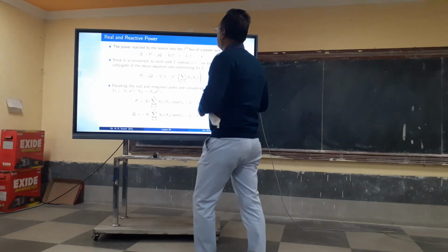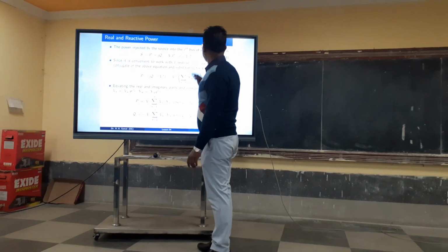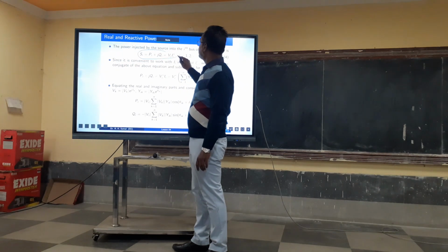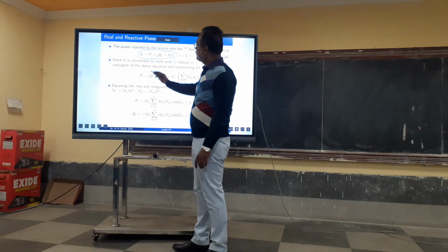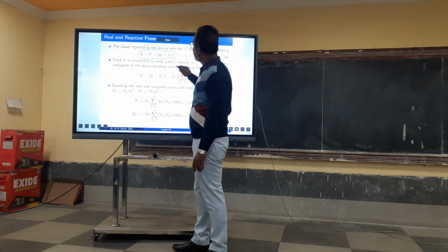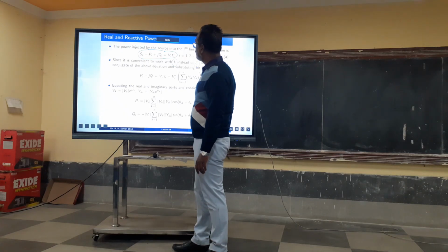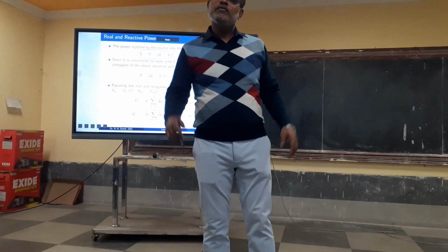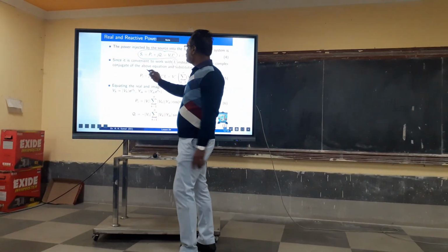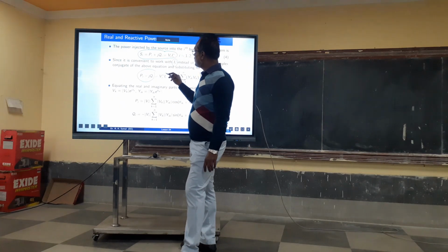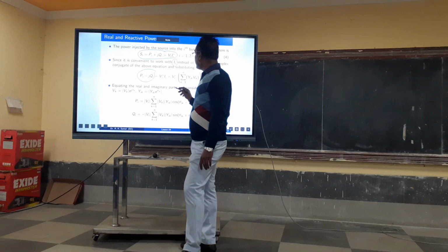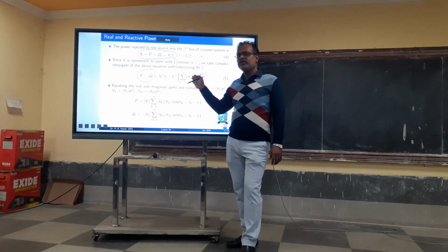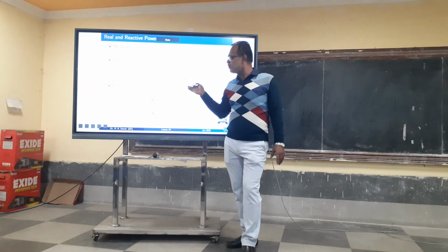So total power injected at the source is given by Si equal to Pi minus jQi. Since we are working with the current, we take the conjugate of both sides. You know the complex conjugate of P plus jQ? P minus jQ. That's the complex conjugate. So that is equal to simply taking the conjugate of this side, which is Vi conjugate into Ii. This is the current value. It's nothing but a simple summation of voltage into admittance, or voltage by impedance.